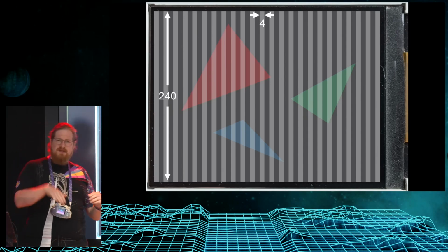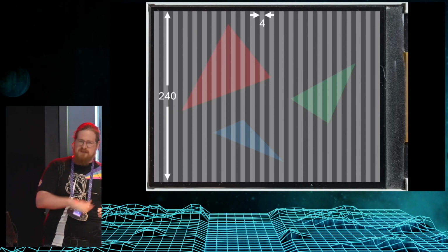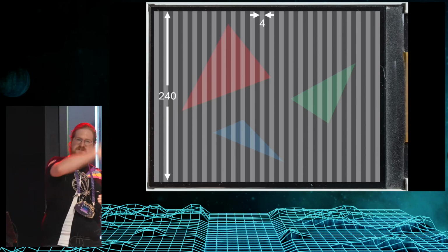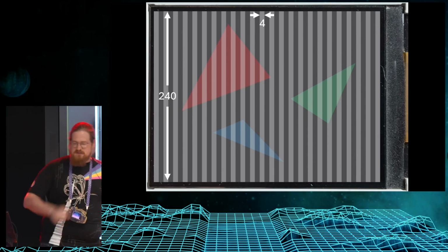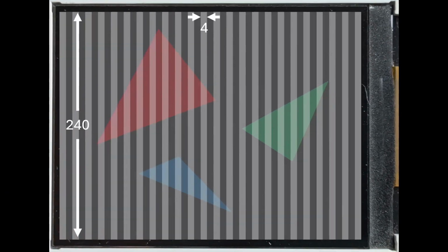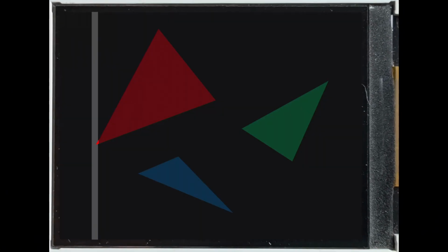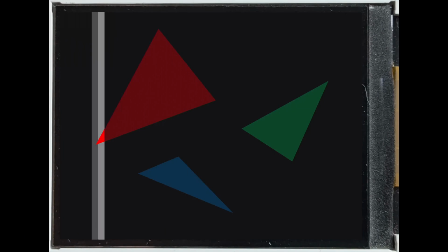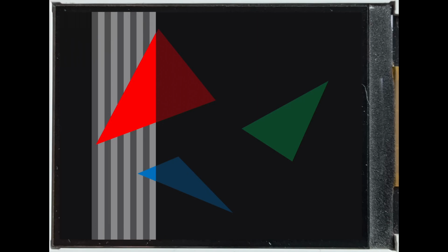And this is also what I'll do for rendering. So far I've been talking about scan lines as you're used to on a television, but I'm scanning vertically. Calculations are the same, just flipped in order. And rendering we'll be doing strip by strip. And every time a strip is ready, we'll send it over to the LCD screen. And eventually you'll find that you'll have to draw multiple triangles, and you'll have to draw a triangle over multiple strips.